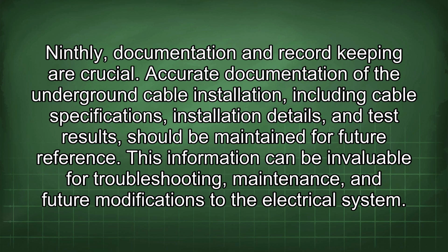Ninthly, documentation and record keeping are crucial. Accurate documentation of the underground cable installation, including cable specifications, installation details, and test results, should be maintained for future reference. This information can be invaluable for troubleshooting, maintenance, and future modifications to the electrical system.